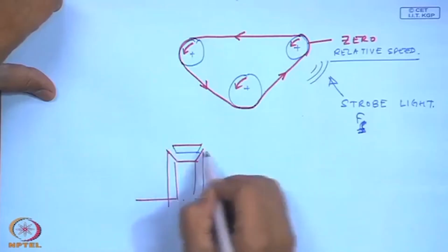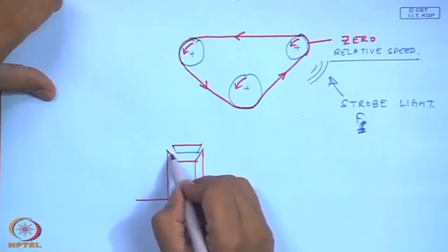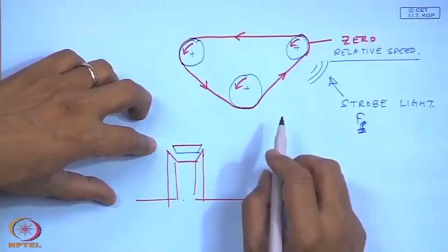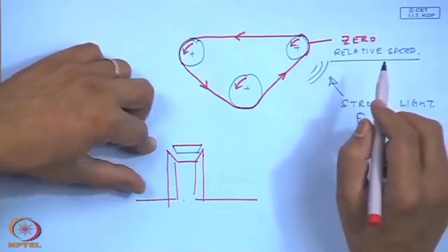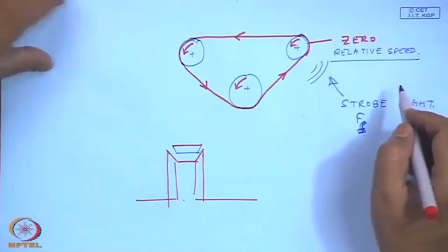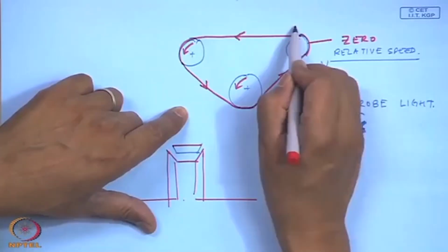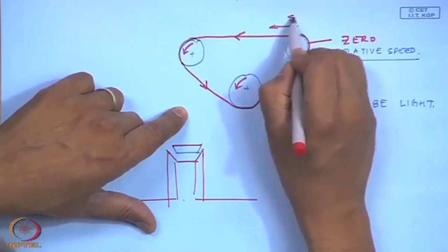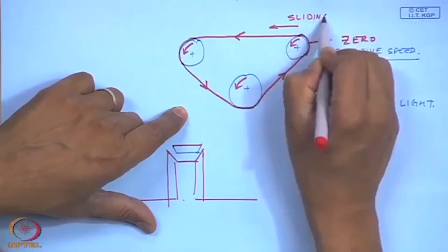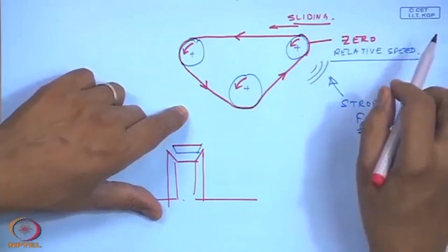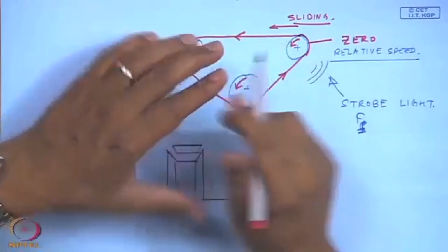Okay, so, I have exaggerated this gap. So, between this the belt would look stationary, and such can be used to detect looseness. If they were not stationary, this would gradually look to be sliding on the stroboscopic image. And those of you who have seen the engine fan belt, if it is slipping over the pulley, they shoot a strobe light onto the engine fan belt and find out these kinds of things.